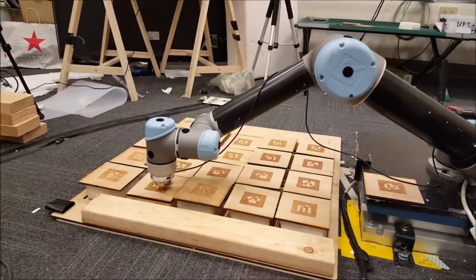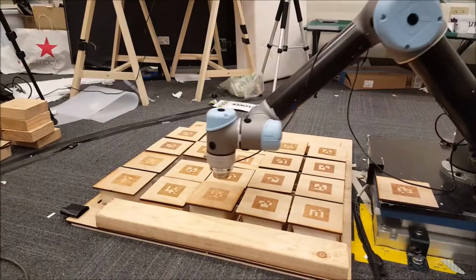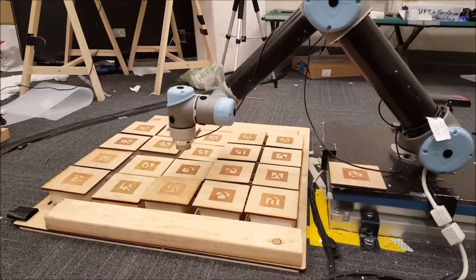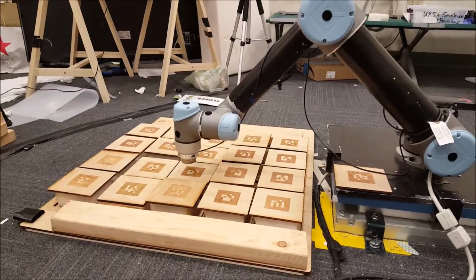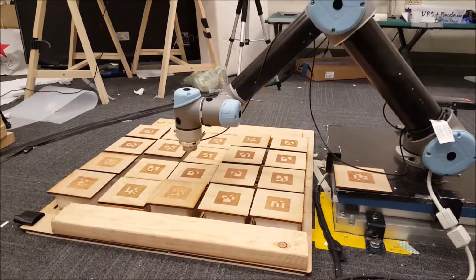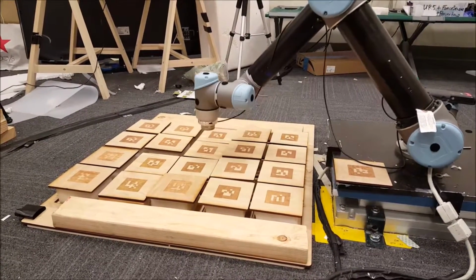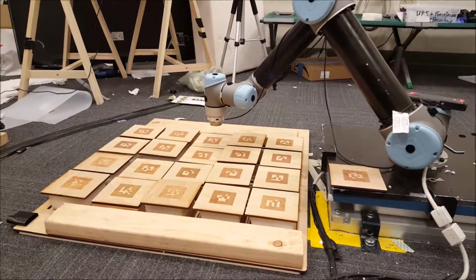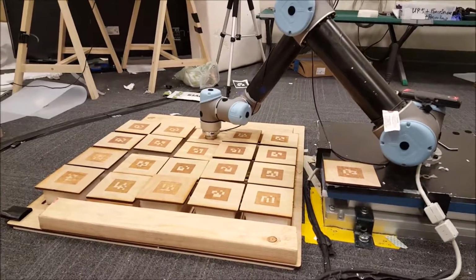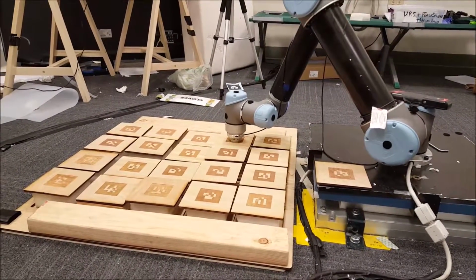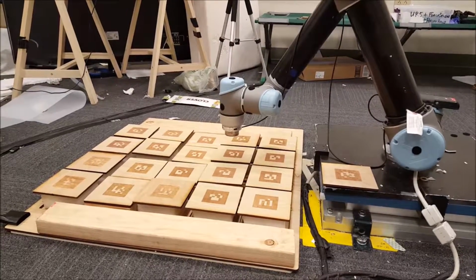The way we are reading the force values is we make sure that the force sensor is calibrated and gone over a certain threshold force, and then after that is reached, we map the slope of force versus time, and by looking at the steepness of the slope, we're able to tell whether or not the block is wood or foam. So, as you can see, the UR5 is just traversing the grid in a snake-like motion.